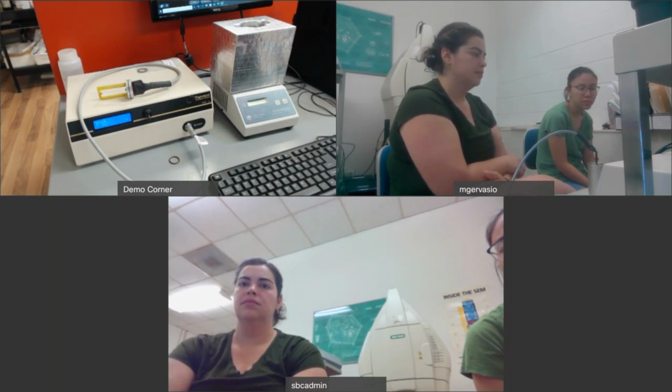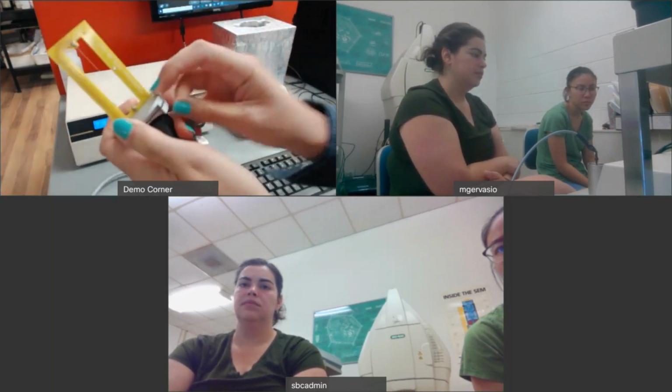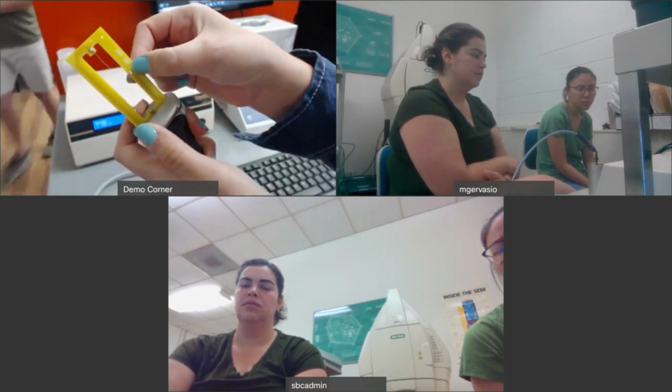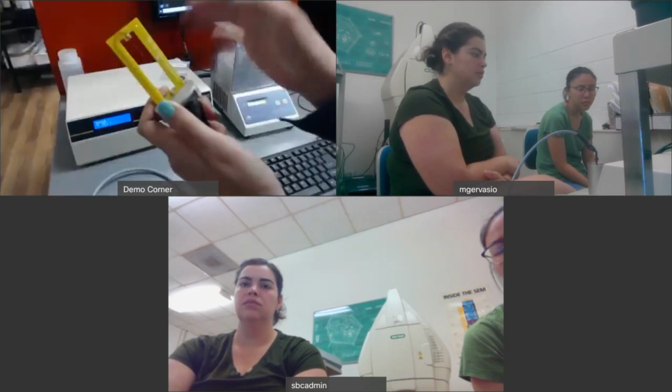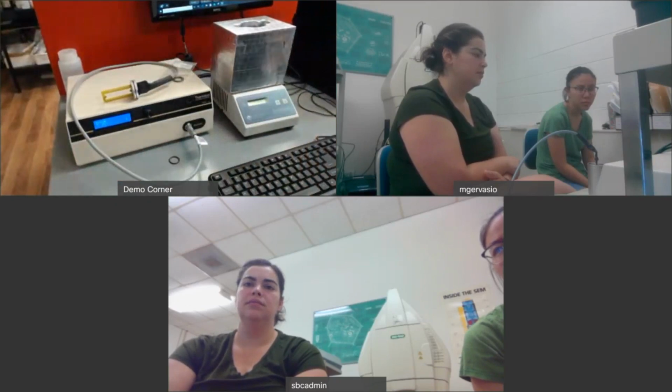then you cannot measure. In that case, if you want to protect your sensor, or in case you want to measure nanofluids or something, you can put something simple like transparent nail polish on the solder joints and the temperature sensor to protect it, and then you will be able to measure. But it's small details. If you're sure that the temperature of your fluid is stable, that is very important for the activity.